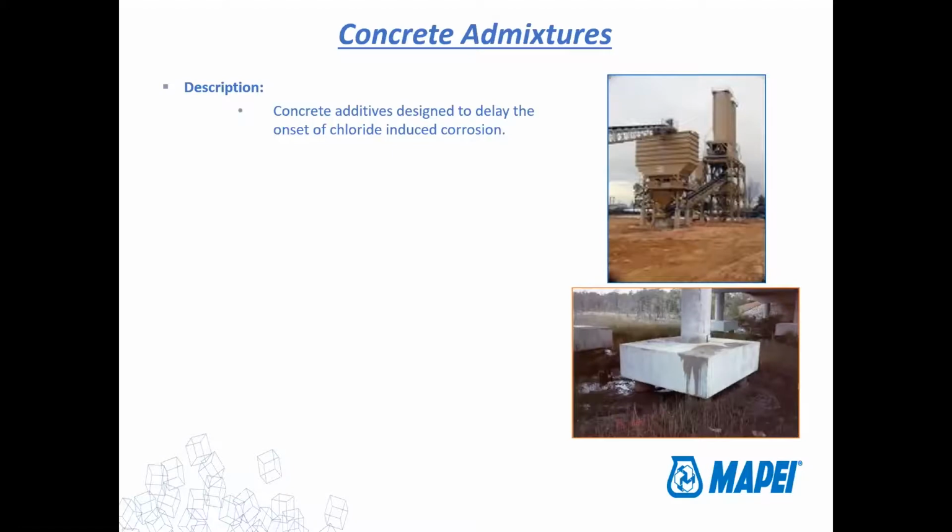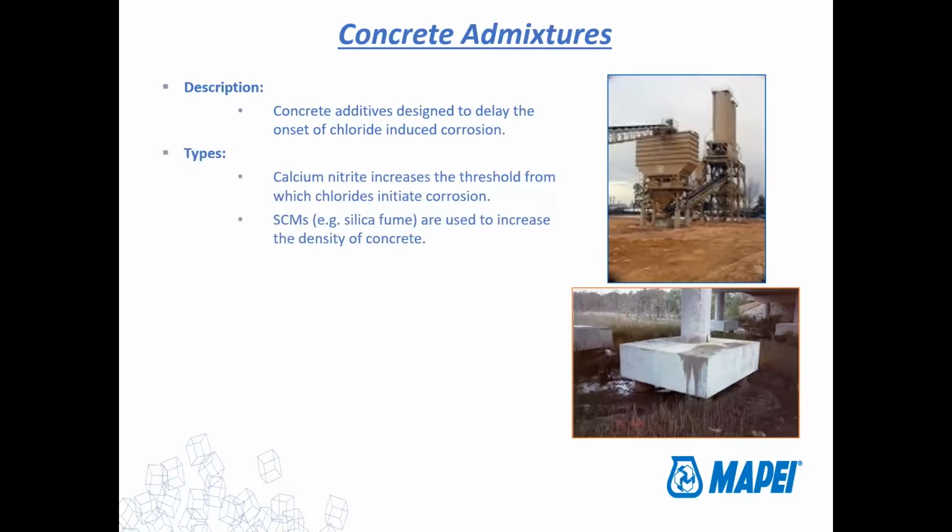I don't work with a whole lot of fresh concrete, but I'm sure they're adding these to fresh concrete as well. Really, all that it is is nitrites. It's calcium nitrite. It gets added to the bagged concrete, or added at the mix plant in the case of new, fresh, large-batch concrete.